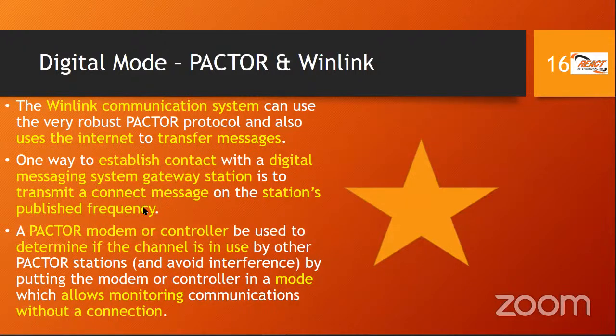Also, if you want to know if the channel is in use, you can put the Pactor modem or controller in a mode that allows you to monitor without actually making a connection. So you can see if it is busy. On the newer modems, there's actually a display on the front that will show you the waterfall, and a readout that will tell you if the frequency is busy as well. But the point for the exam is that you can tell if the channel is in use by putting it into a monitoring mode without actually requesting or making a connection to another station.